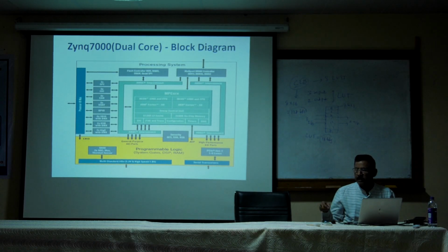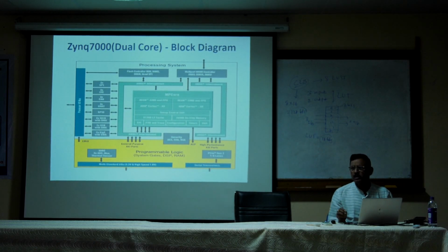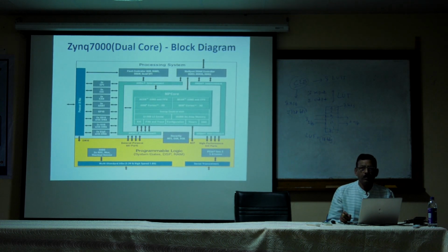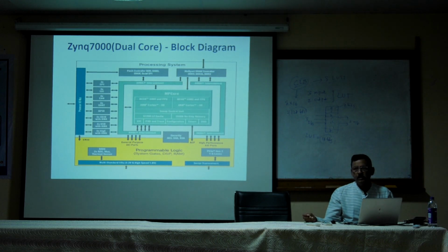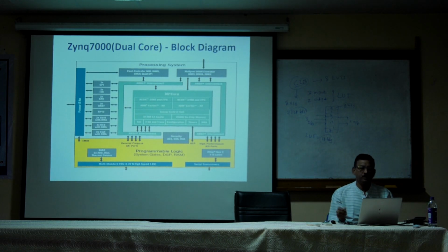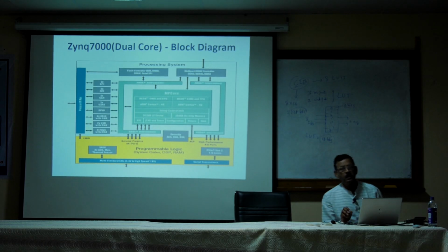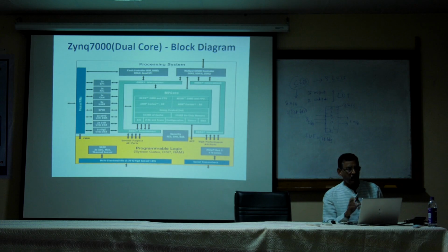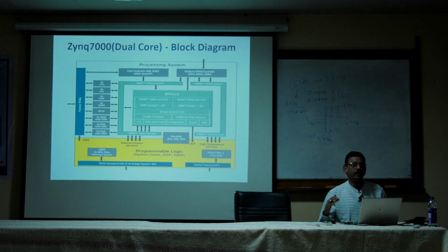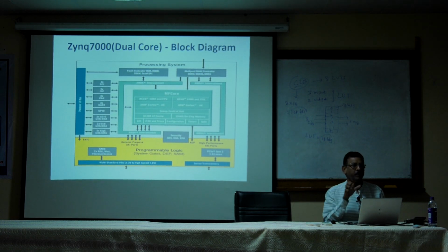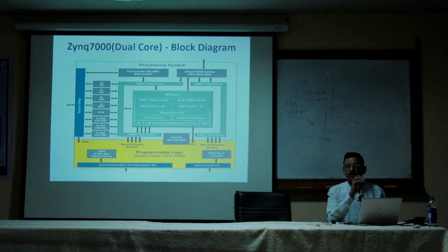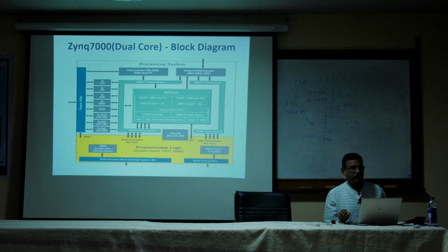Through I2C we can connect any device. Suppose you want to connect a camera, we can connect the camera to this FPGA. Or through USB, you can connect any USB-enabled device to this system through these interfaces. That means it is a powerful FPGA we can use in embedded applications, with a lot of external communication interfaces, plus FPGA fabric and processing cores present inside this FPGA system.